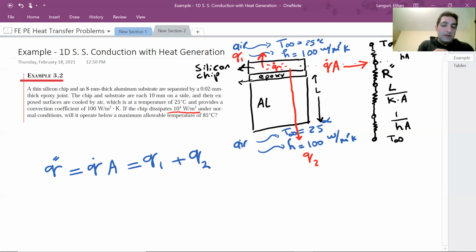Because remember, it's a steady state. SSS stands for a steady state. It means that you're not accumulating heat in any layer. We are not sinking heat in any layer. So heat generated in a steady state should leave the silicon chip. That's why we can continue working and temperature hopefully remains at set point. If this is the case,